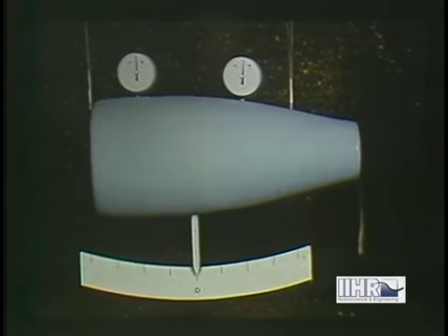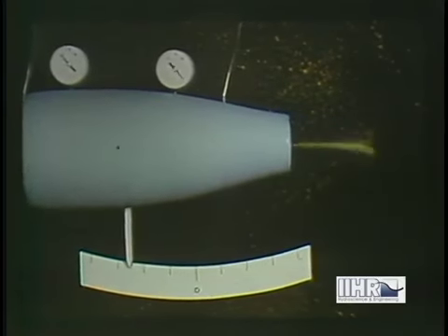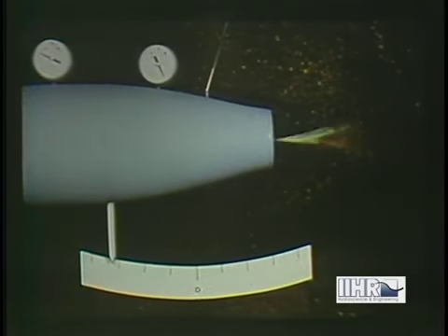In this cutaway model of a simplified jet engine pod, the propeller operates in a larger section than if it were in the open, and hence, as seen from the continuity and energy equations, at lower velocity and higher pressure. For comparable reasons, the high-velocity jet will emerge from the rear of the enclosed unit at the same pressure as the surrounding fluid. However, the unit will be displaced in the opposite direction by the reaction to the force required to change the flow from low to high velocity in accordance with the momentum equation.